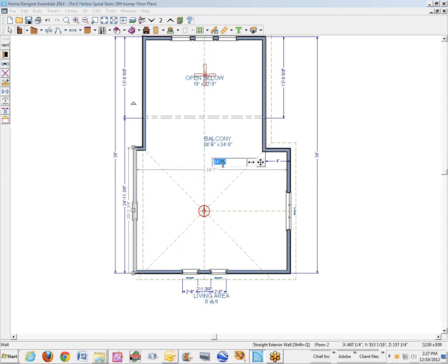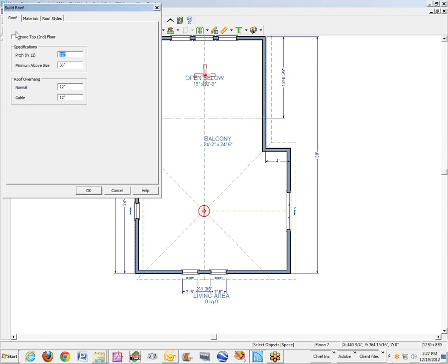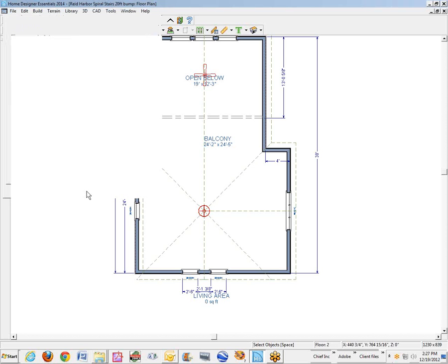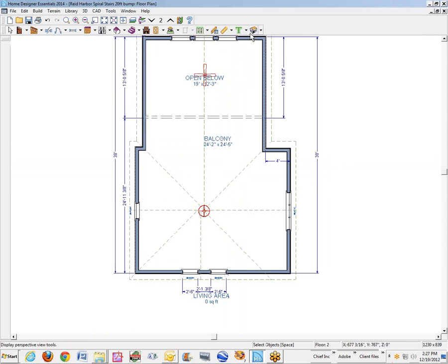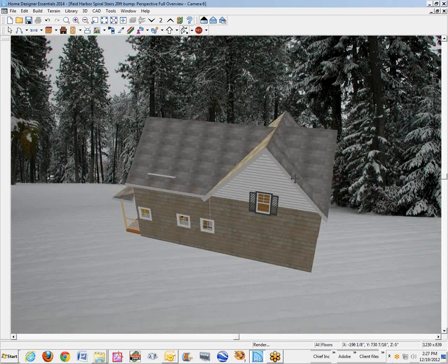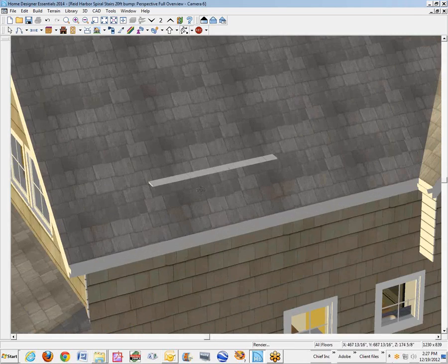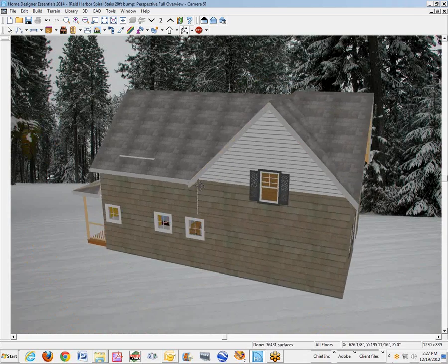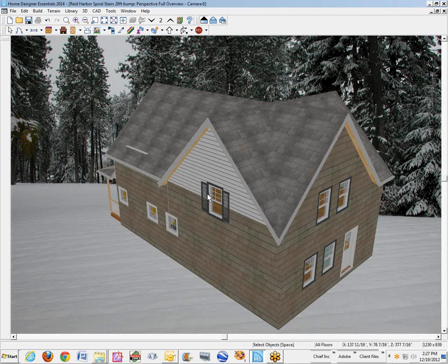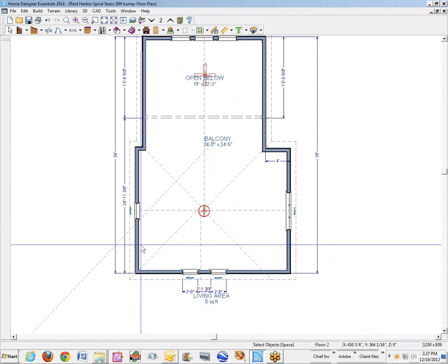Let's see if I can bring it down to 24.3. All right, then I'm going to go to the build roof dialog and build roofs again. And of course then it builds the roofs based on this false thing that I did. And yeah, okay, it's filled everything in. I don't know why this wall here is sticking through. That's a secondary matter. Now, the next thing I did, of course, this is not what you wanted. It could be what you want, but that'd be up to you.